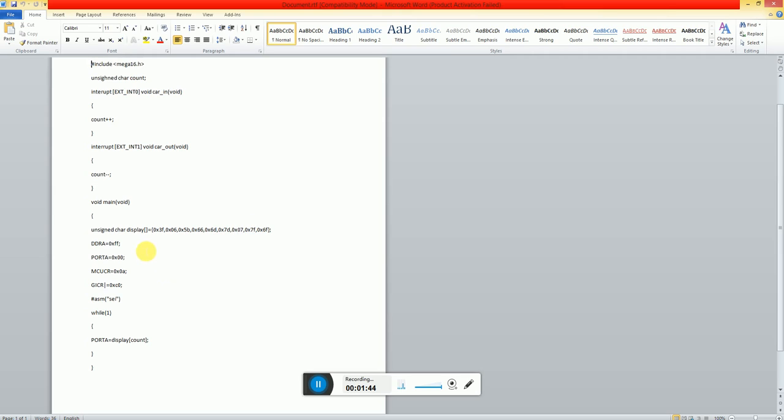All the values going to the 7 segment display should be high, meaning at least 5 volts or the required voltage to turn the LED segment on. If it is common anode, just take the opposite of these values.